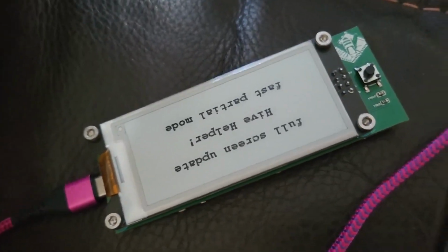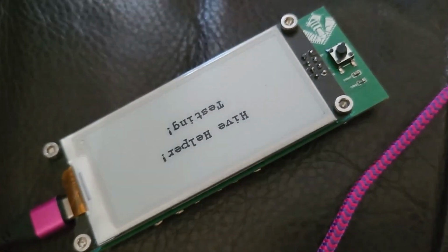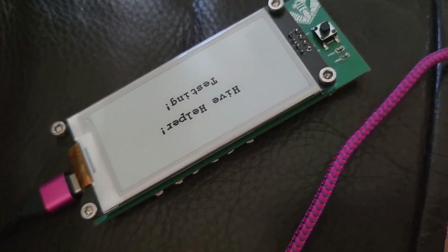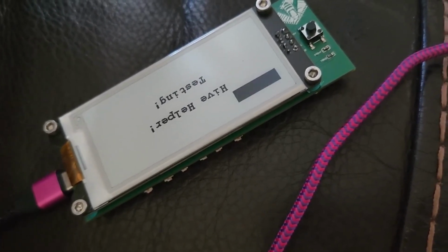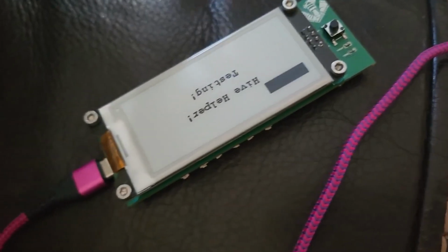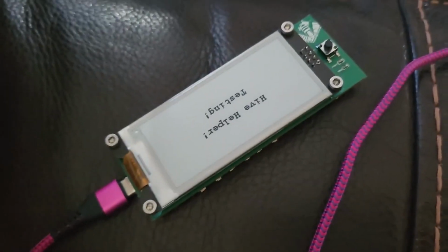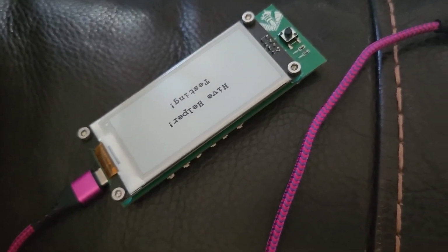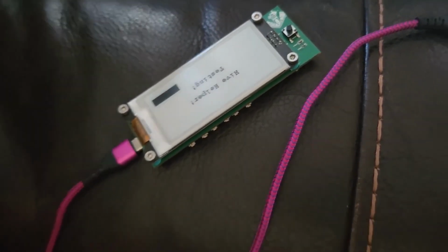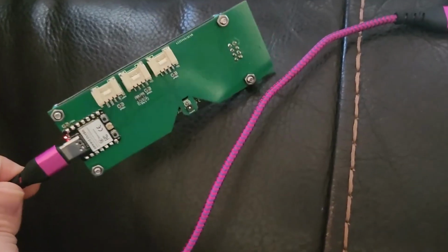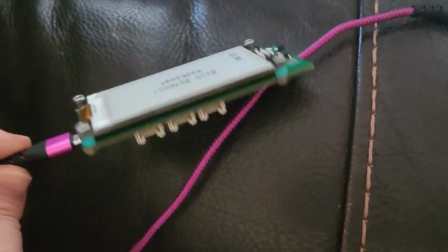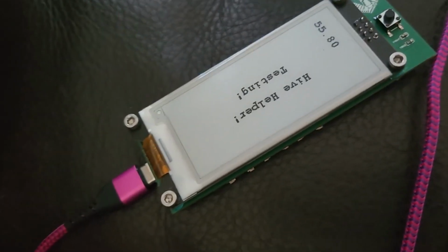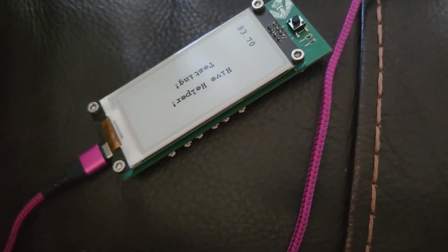Hive Helper. I need to figure out how to flip the screen so that it works like this, but that's great. Looks like it's working at least. And I already confirmed SDA and SCL are in the right spots and everything. So the AHT20, assuming I didn't mess up the solder there, should work as well. We'll see. I'm going to unplug this for now and figure out how to flip it.